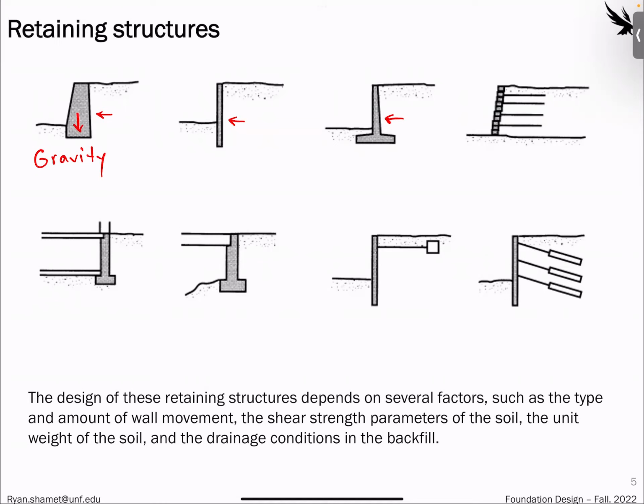But in some cases, if we have pile or sheet walls, so sheet pile walls, like those super long ones, these are relatively thin. And we would need to ensure that this type of material is able to withstand that loading. So we almost visualize this as a beam in some cases. You could picture how if we tilted this whole thing sideways, the loading would look very similar to a beam.